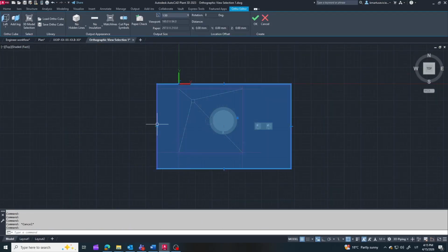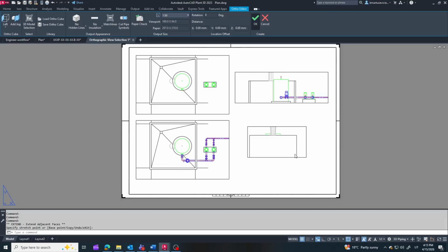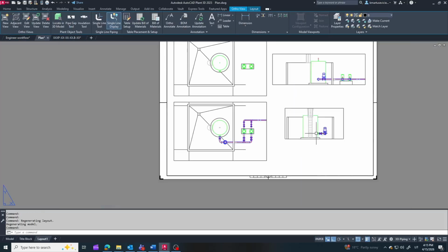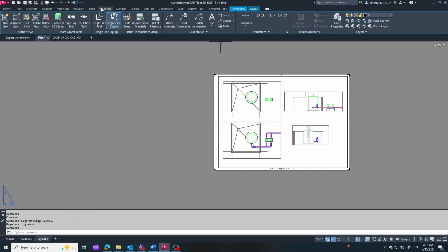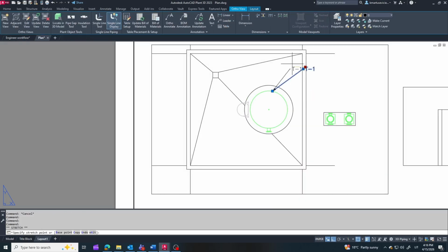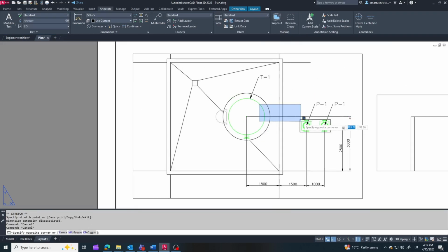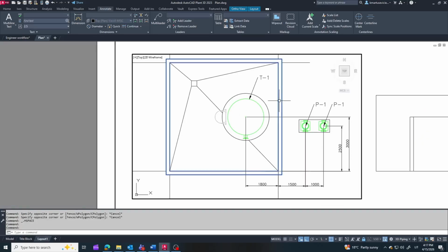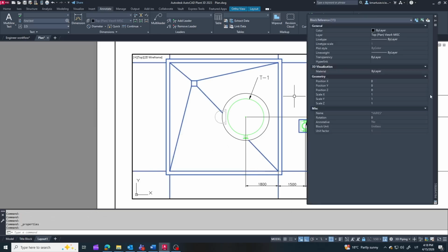Add clear names to each view and indicate the scale. The idea of this drawing is simple. Anyone who takes it should be able to build this unit. The main elements, especially new or important parts, should be drawn with thicker lines. Secondary or less important elements can be shown with thinner lines.